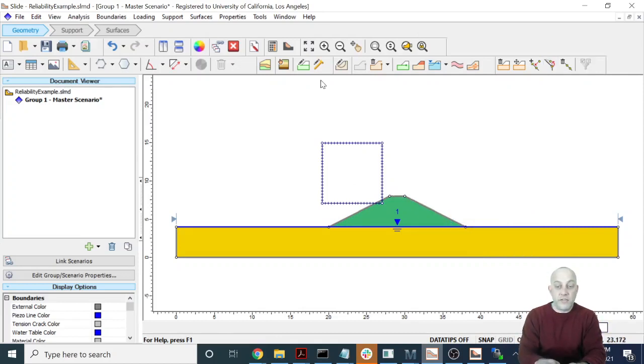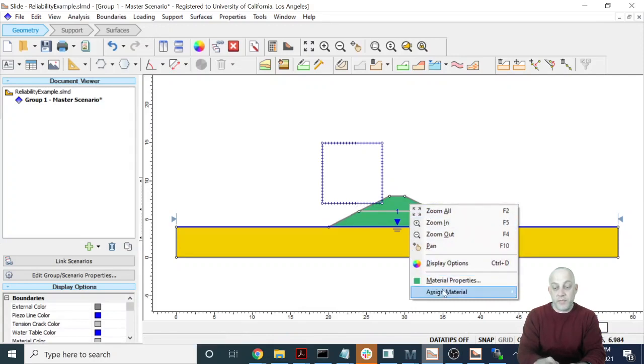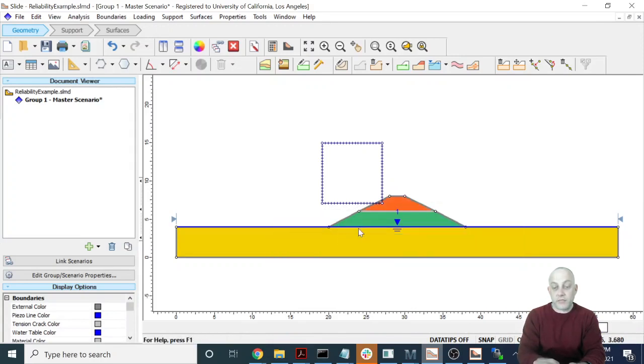Okay, that's what the original levee looked like. And now I'm going to come in and sketch a new material boundary. We'll go straight across and then up to here and over. And now I'm going to do material 3. Okay, and so if we wanted to analyze the condition after stage 1 has been added and the clay has consolidated fully under the weight of stage 1, and now we've added stage 2, what we want to do is take away